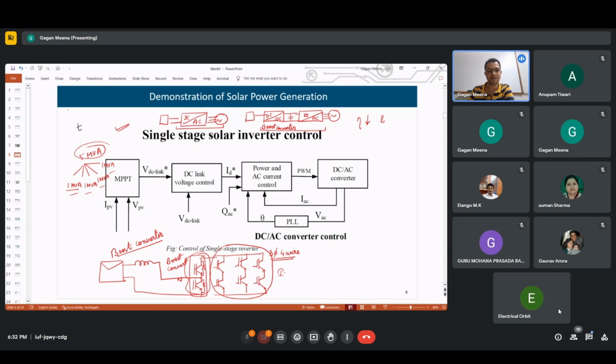So we had seen, I think in previous weeks, there is a relationship between depth of discharge, number of cycles, and discharge rate also. As the depth of discharge increases, the number of cycles reduces. The battery life reduces. You were all correct, depth of discharge should be low. We don't want high depth of discharge. If it is high, it will degrade. So depth of discharge should be low, then we can increase the battery life.